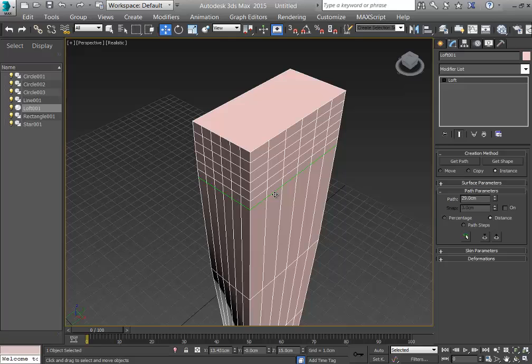Points of change are accordingly where you are, and if you look at it here at 29 centimeter, I have a change, and that means that when it reaches 29 centimeter, it will change into exactly a rectangle, and the change starts from 15.2. So it's starting from 15.2 centimeter as a circle and changing into a rectangle up until the 29 centimeter.